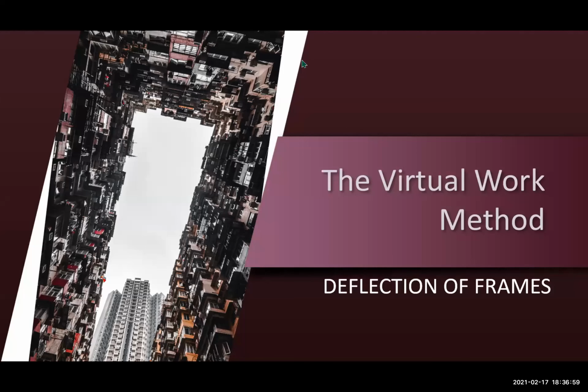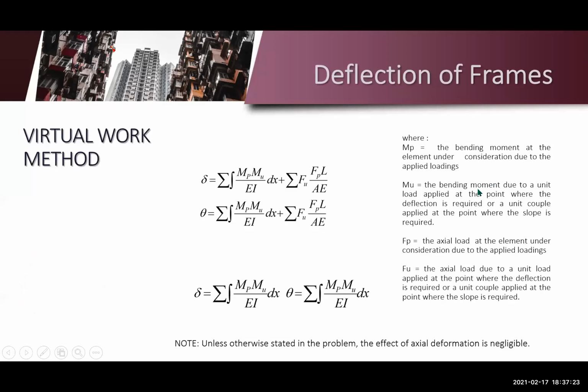Okay, so another application of your virtual work method is for the deflection of frames. So basically, yung equation na gagamitin natin sa frames is a combination of the equation that we used for your beams and truss. Because frame is both subjected to bending and axial force. So applicable yung parehas na equation. But yung pinaka kino-consider lang natin sa deflection ng frames is the bending equation or itong first part.